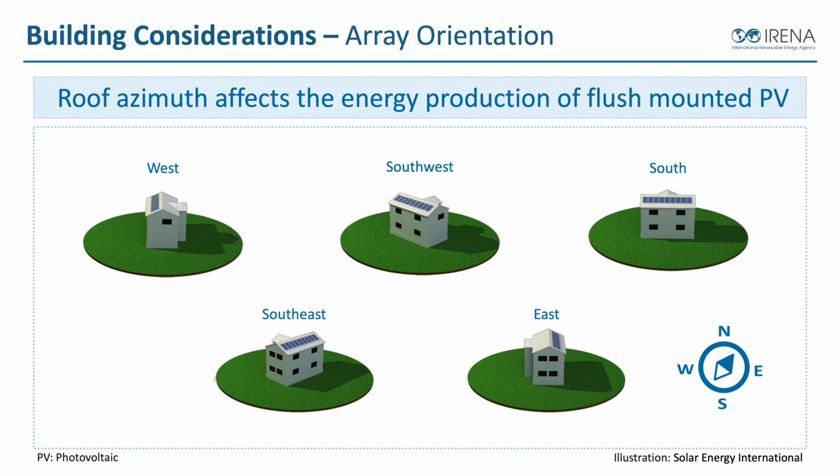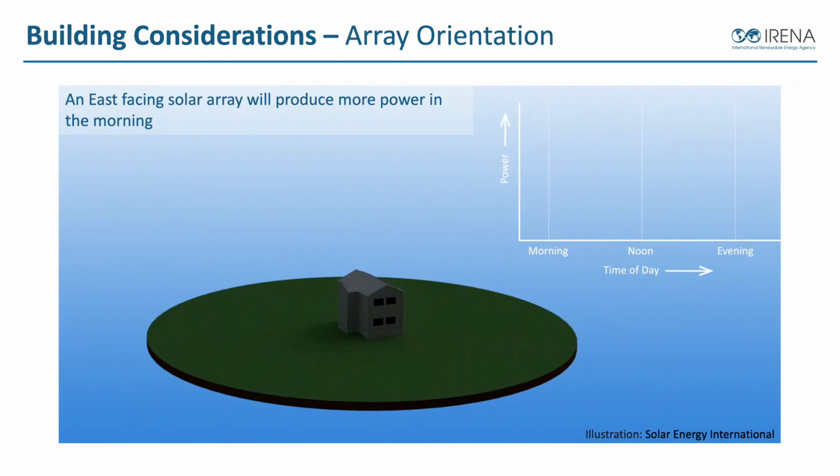As we discussed earlier, the latitude that we're at will impact how much power performance difference we have at these different orientations. So really, most of the time we can utilize the roof that we have in a lot of situations. And so our job is to take a look at the roof we have that's sunny and free from obstacles like shadows or too much equipment, and pick a roof that's going to work best. And then we can determine, based on the roof that we chose, how much energy production we'll actually get out of that location. Now, there's a few things that can vary when we look at these differing orientations, though.